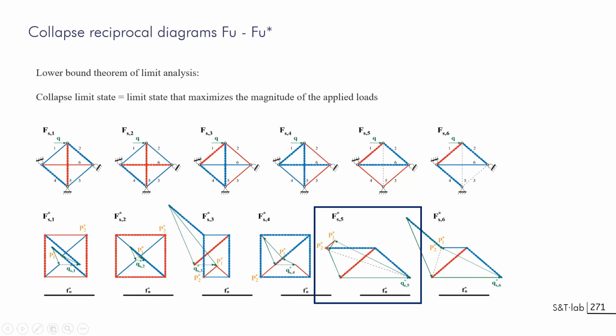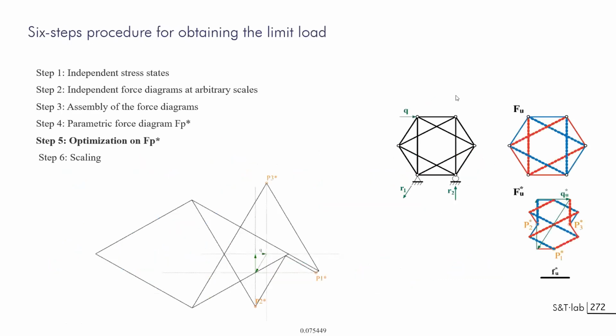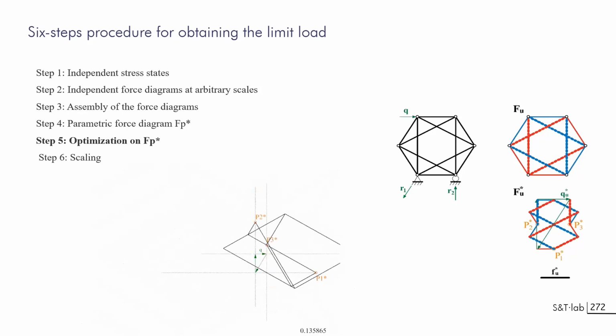As you cannot do this just that way, you could enter an optimization process. And for this, I will take another example in which we will be defining the system here of a complex truss that will be summarized here as a form polygon and a force polygon. And you will see from this how you can play with several parameters that will be linked to the problem. This could be made in an automatic way with a process that will be linked to optimization. And you can see that the force polygon is getting smaller and smaller and smaller. And at the end, that will be adjusted for this. And this is the final solution, as you can see here.